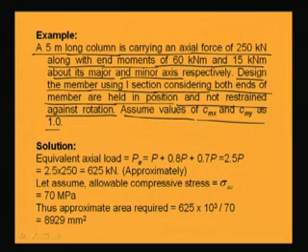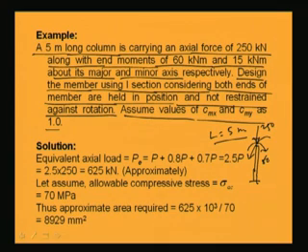So, what we have seen here, that length is given as 5 meter and the column is having moment in different direction along with load. Load is 250 kilonewton and one moment is 60 kilonewton meter about major axis and 15 kilonewton meter about minor axis, and you have to choose an I section, it is told, and values of CMX and CMY have been given as 1, and it has been told that both ends of the member are held in position and not restrained against rotation, that means hinge type things. Okay. So, L will be